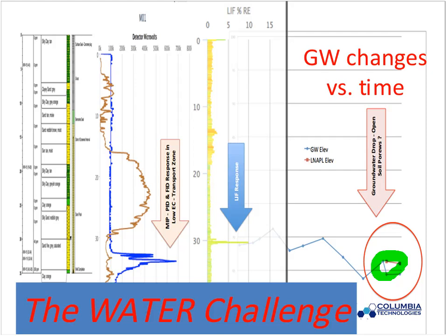ICRC does a great job of case studies of looking at this in multiple conditions. You could have perched water, you could have confined perched LNAPL, confined LNAPL, and this could easily be moving underneath our groundwater table. In this case, we're just moving along the top of the groundwater table. As the pore spaces open up, the LNAPL can move.